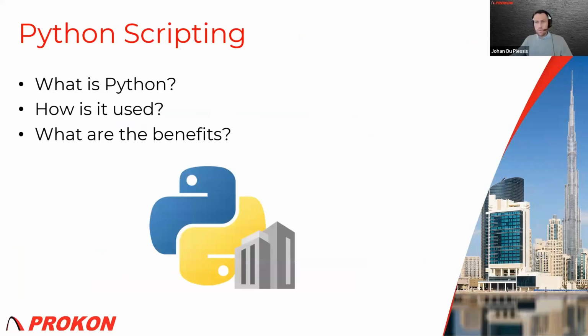Right, and then we've got the Python scripting interface, or PySumo as we call it, and that's quite a big improvement and adjustment that we've made to Sumo. And this really, I believe, similarly to the solid finite element, takes Sumo to the next level, because with the Python scripting interface, you can now automate some tasks in Sumo and really reduce your modeling time quite significantly.